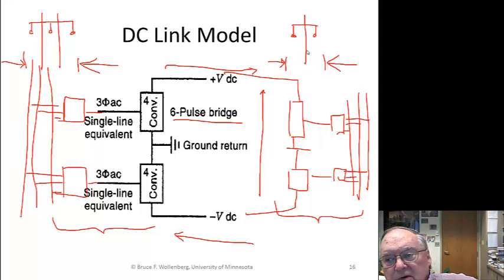Now it turns out that yes, it's cheaper, but in order to overcome the extra cost of what we call the rectifier and converter stations, you usually build these for very long lines, so you have a big enough savings so that even when you add in the cost of the converters and rectifiers, it's still cheaper to build.